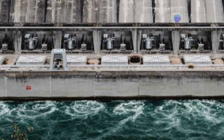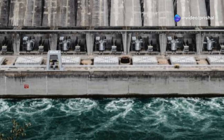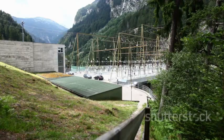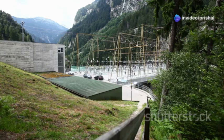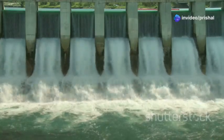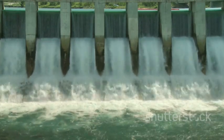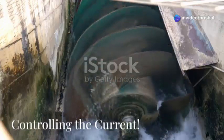Head is a critical factor in hydropower plant design because it directly influences the type of turbine we choose and the amount of power we can generate. Different turbines are suited for different head heights. Understanding head is key to unlocking the full potential of hydropower. It's the foundation of efficient energy generation. Now that we've got a handle on the power behind the flow, let's talk about how we get the water into and out of our hydropower plant safely and efficiently. This involves careful planning and engineering.